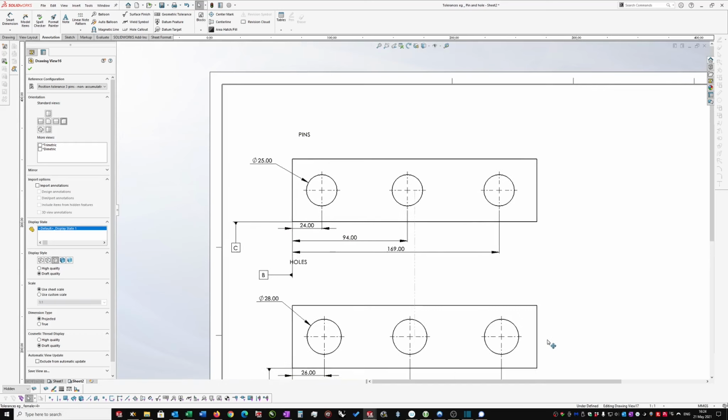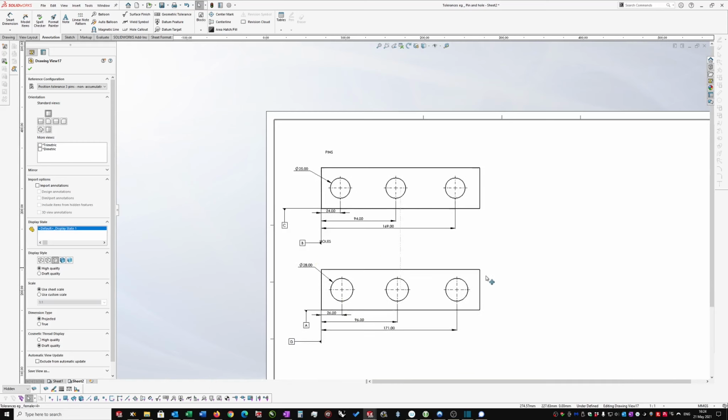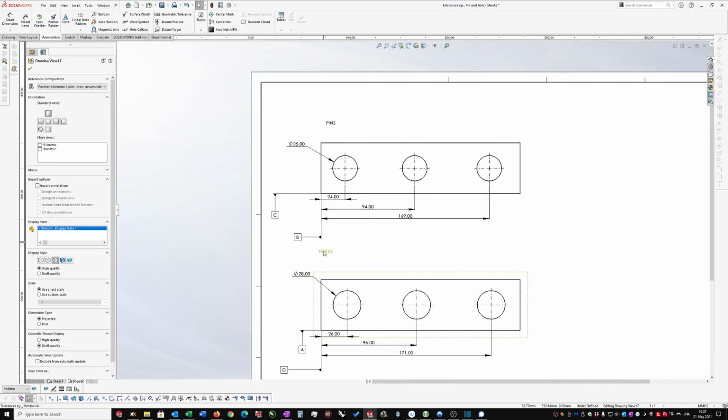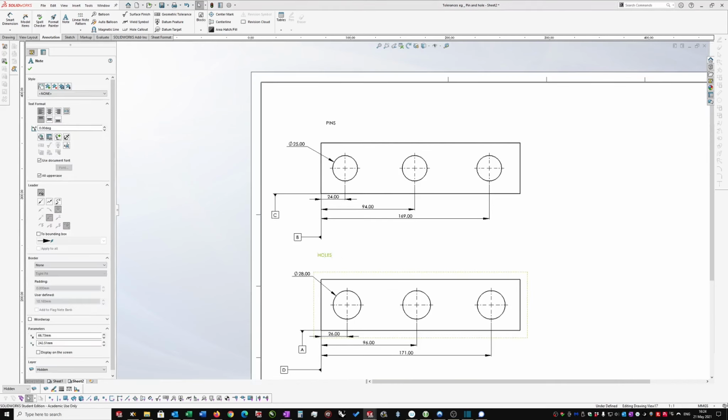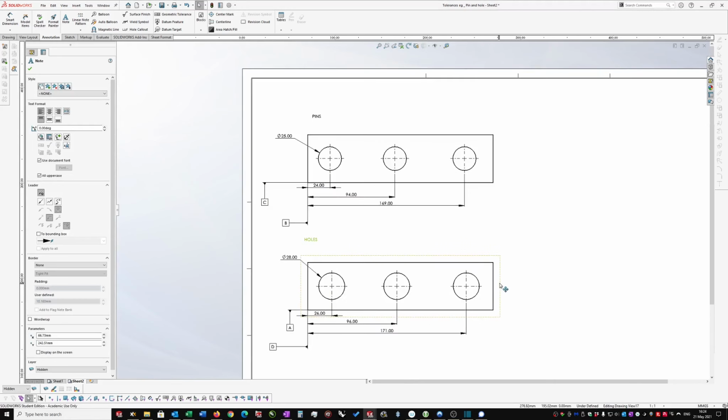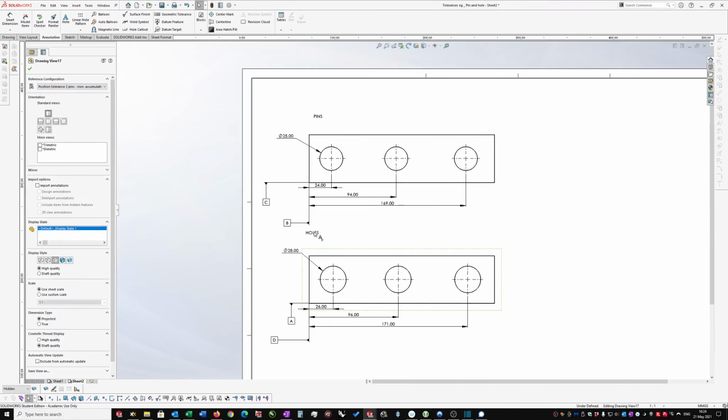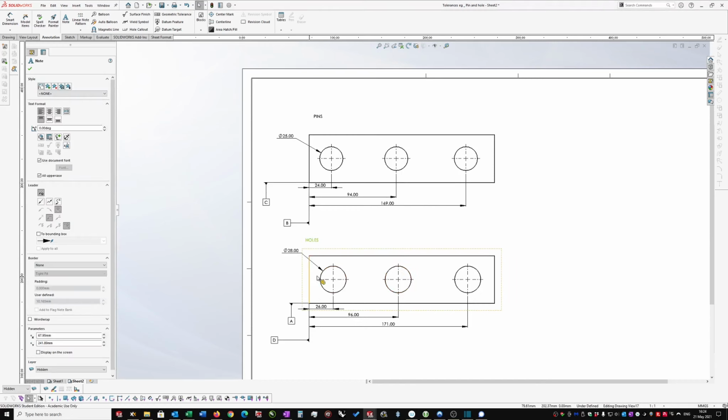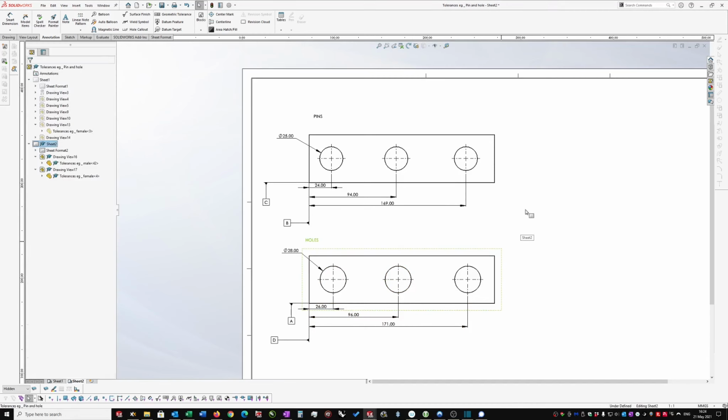So that's what non-accumulative tolerancing, or dimensioning from a datum, achieves for you. I'm using exactly the same tolerance limits. I'm just selecting the datums as the starting point, and so that limits the amount of error that I can encounter. Okay, so hopefully that explains why dimensioning from datums is so important.